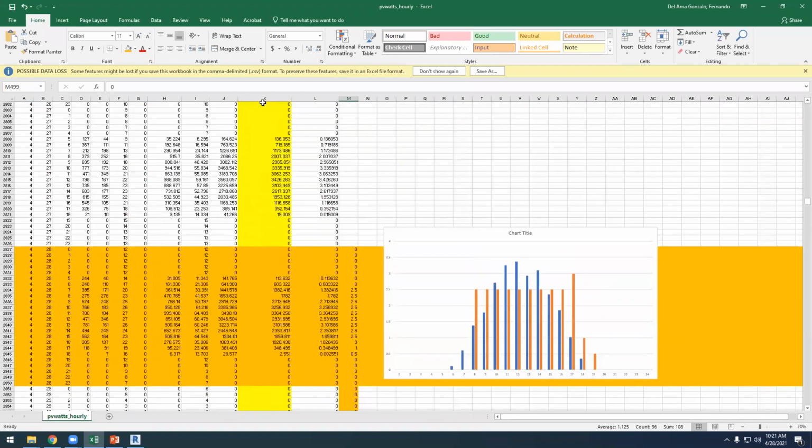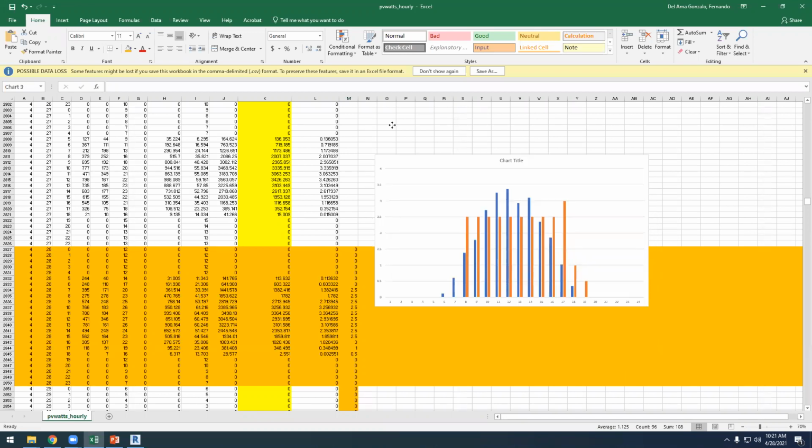Okay, so we will do that with PVWatts to calculate the energy production, and finally, by carrying out this Revit analysis, we will find the demand, and we will have to compare the energy production and the energy demand. In this building, the energy production is going to be like 30% of the energy demand, kind of. That should be the final result, because this is what they told me.